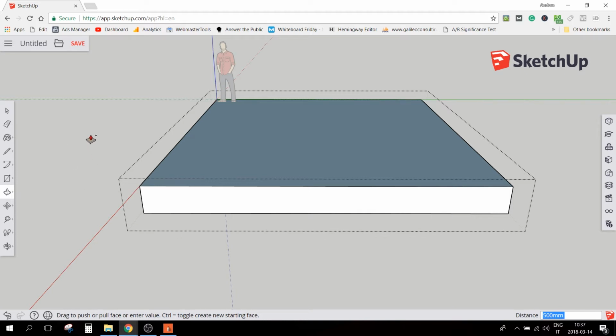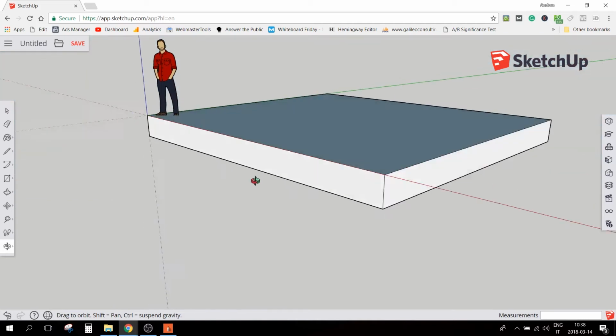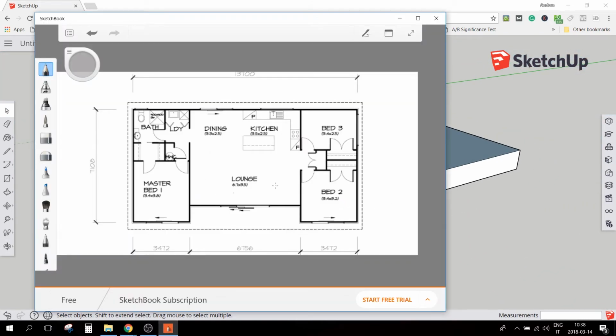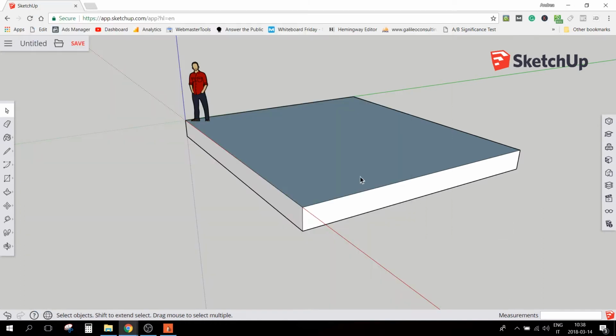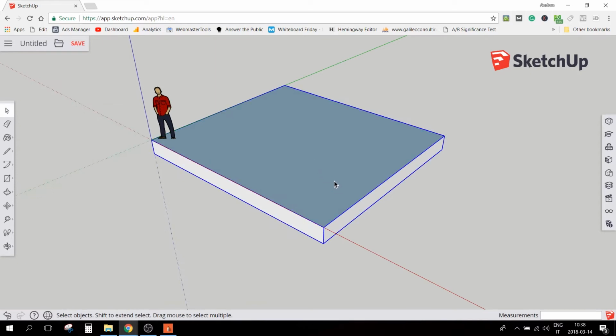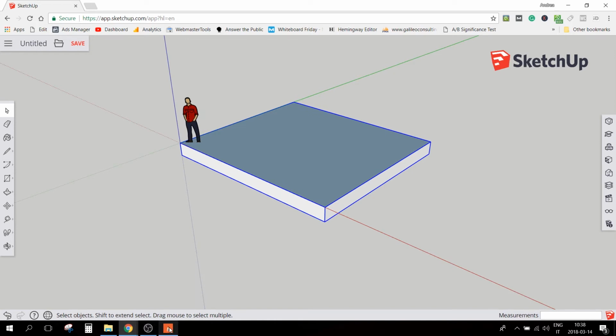Now I press space to get back the arrow tool, selection tool, and I click out of the solid, boom. And now we have this thing. This is our foundation, again, only for this part here. I just made a foundation slab, you see, and again, this is just one object. Now what I want to do, I want to add the proper measurements here for the walls, to support the walls. So again, double click, I'm inside the object.